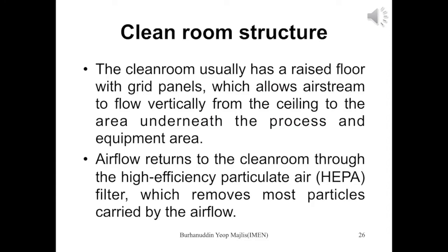So the clean room usually has a raised floor with grid panels, which allow airstream to flow vertically from the ceiling to the area underneath the process and equipment area. And airflow returns to the clean room through the High Efficiency Particulate Air filter, called HEPA, which removes most particles carried by the airflow.